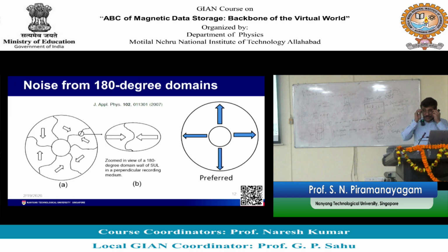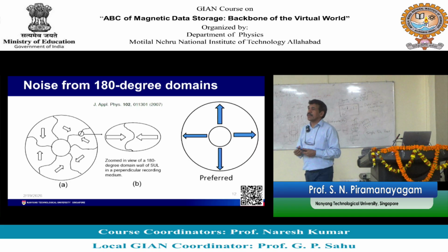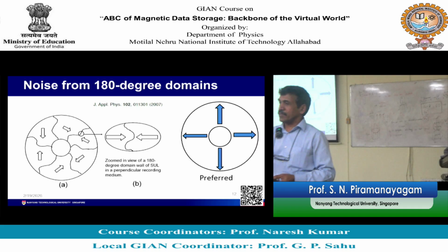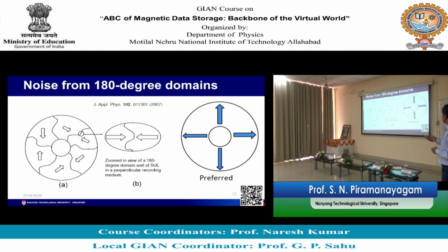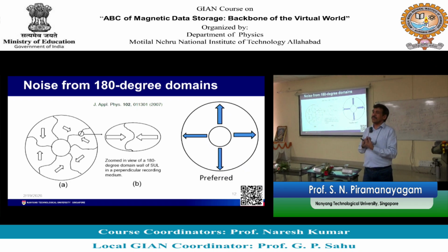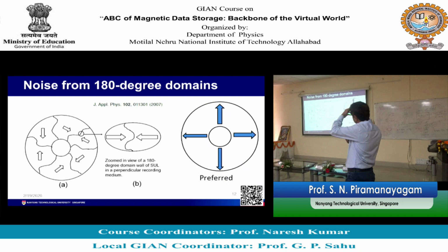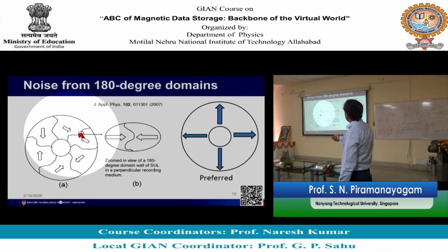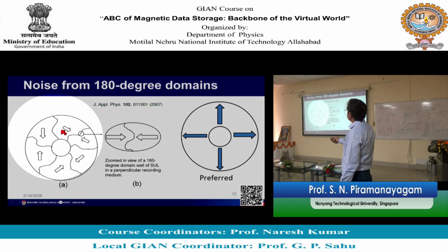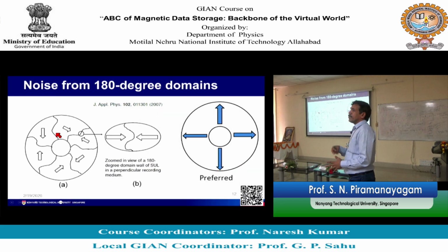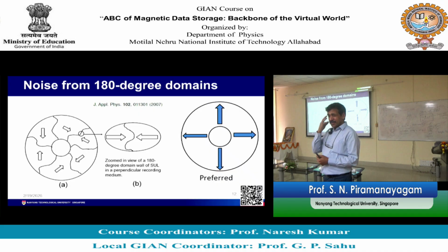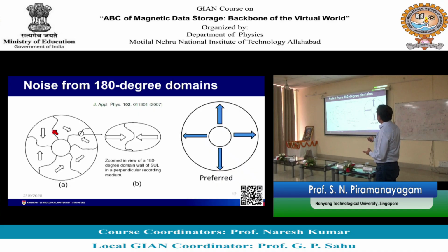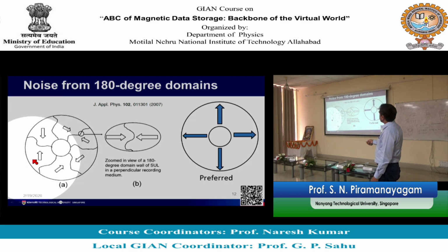Okay. So, this brings us to the point of soft underlayer noise and also to the question that you asked, right. You asked why the thickness cannot be large. So, if thickness is large, you are going to generate more magnetic field out of the soft underlayer. Okay. Let us say this is how the disc looks like and you have deposited a certain soft magnetic underlayer. The soft magnetic underlayer is a normal thin film, so it will form multi domains. Okay. So, let us say it forms domains like this. Okay. So, there are some domain with magnetization in this direction, some like this and so on.